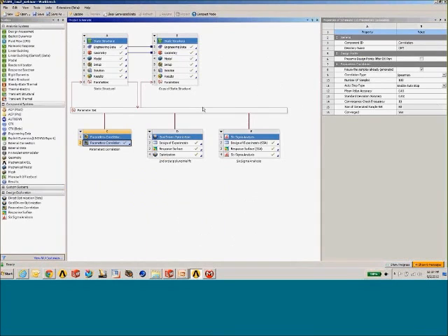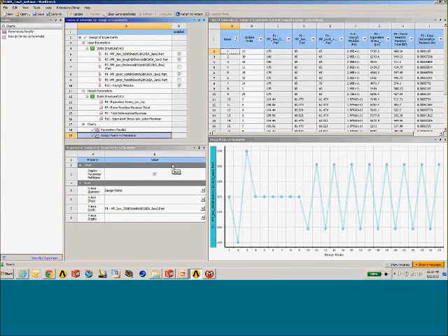So we've identified our critical parameters now, and now we can utilize that list to try to do some predictive work. Two different ways we can do this. One is to use the goal-based optimization tool. We grab that from the list, drag it onto the project page, and open up the design of experiments page.